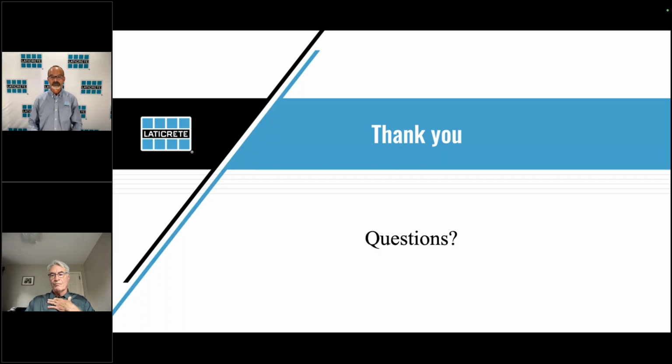Excellent. Do you need a center pedestal for the 24 by 48 pavers? So 24 by 48, you'll have 1 in each corner and 2 in the middle. Not in the middle of the paver. So if the paver's running this way, 24, but 48 towards you, it's going to be pedestal, pedestal, pedestal. So basically 3 pedestals in line going one way and 2 on the other side.